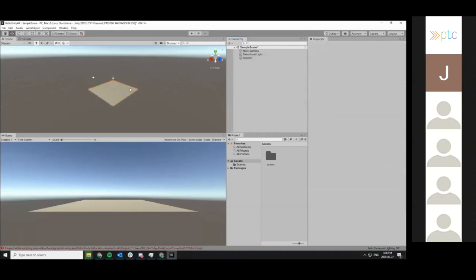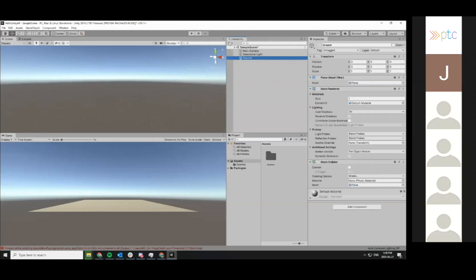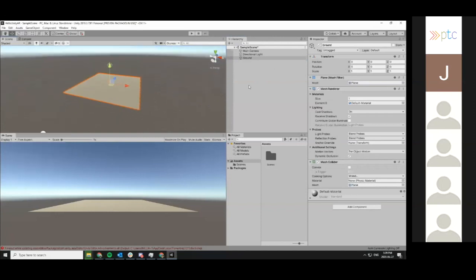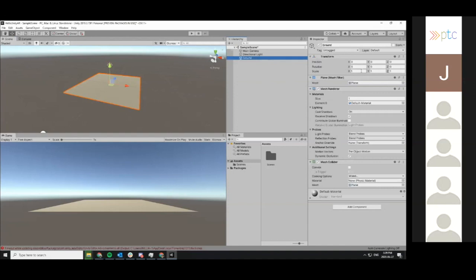We're going to want to make sure it's in view, because sometimes you might be looking over here to the side, and you're like, oh, where's the object? So here you go into the scene, and you press F. You can also go to edit and frame selected, and that will bring it into the view like this. So now that you have this ground in the view, we've created the ground. We're going to make it slightly bigger because this is kind of small. So we're going to change the transform, which allows us to set the scale. So set X and Z both to 2.